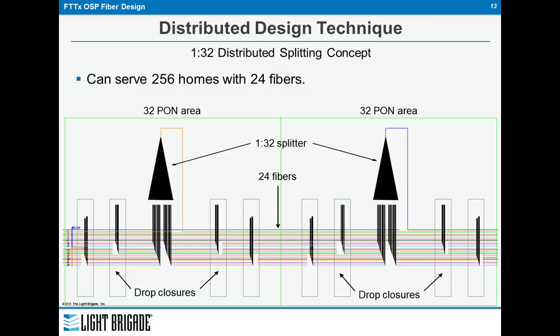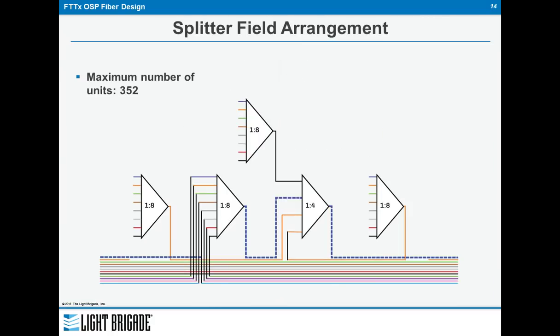This next slide, we moved from a 1x32 split, a single individual 1x32 splitter, a component of that size. We've decided to go one fiber into a 4 split, which feeds a 1x8 split. So in the end, we still are dividing the light 32 times.